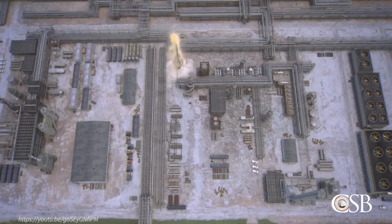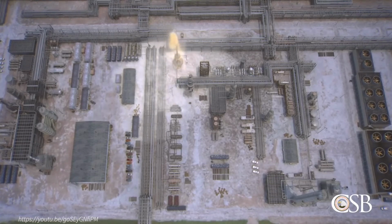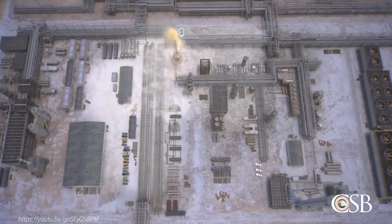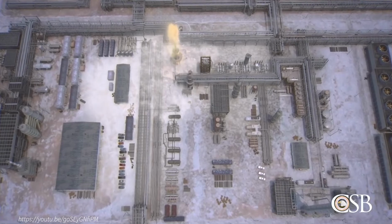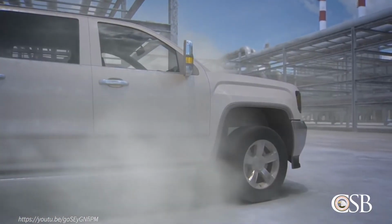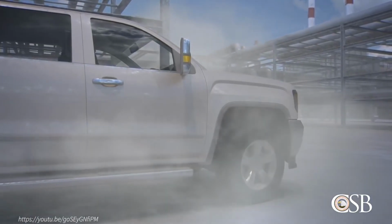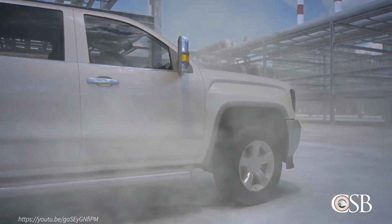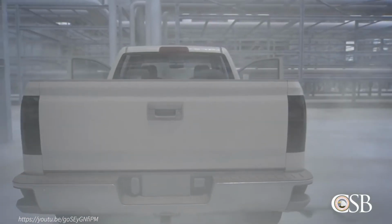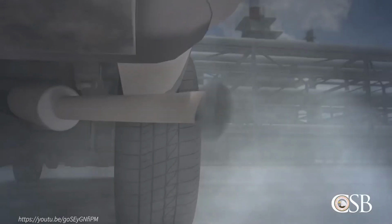The vapor cloud expanded in just 90 seconds, engulfing the unit and the nearby trailers full of workers. About 25 feet from the base of the blowdown drum, two workers were parked in a pickup truck with the engine idling. As flammable vapor entered the air intake, the diesel engine began to race. The two workers fled, unable to shut off the engine. Moments later, witnesses saw the truck backfire and ignite the vapor cloud.